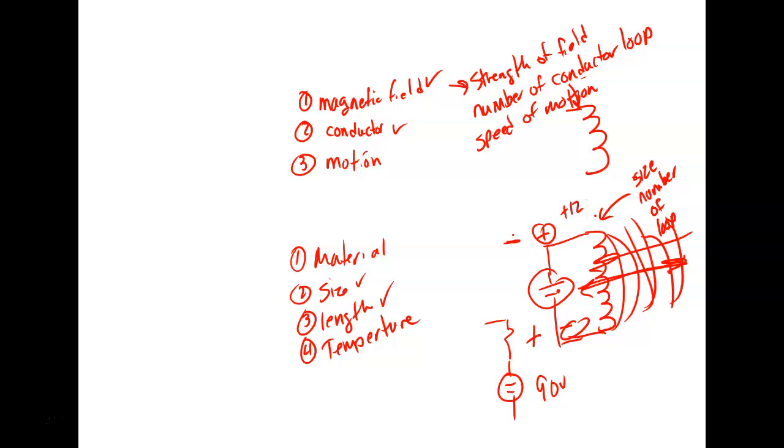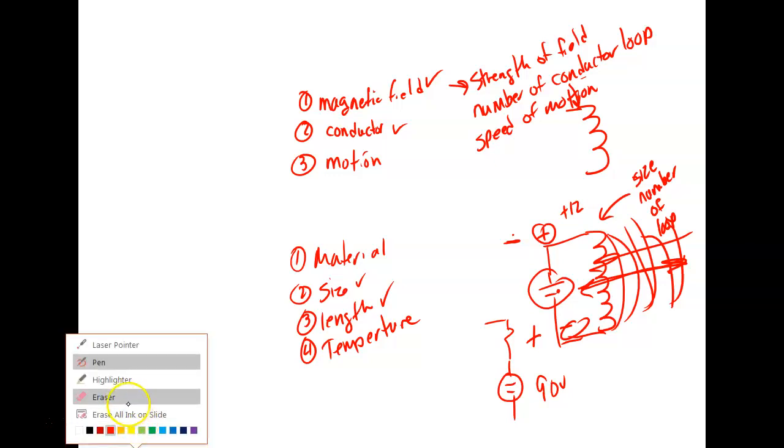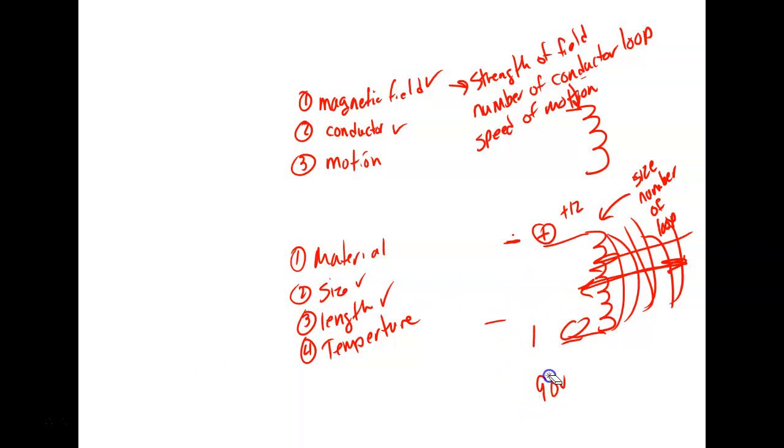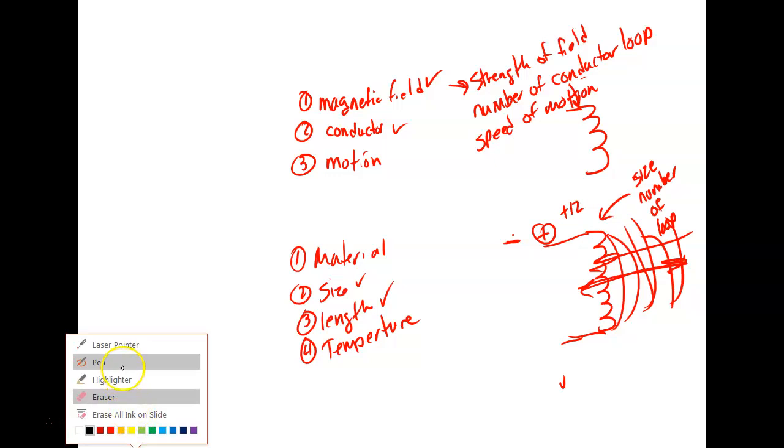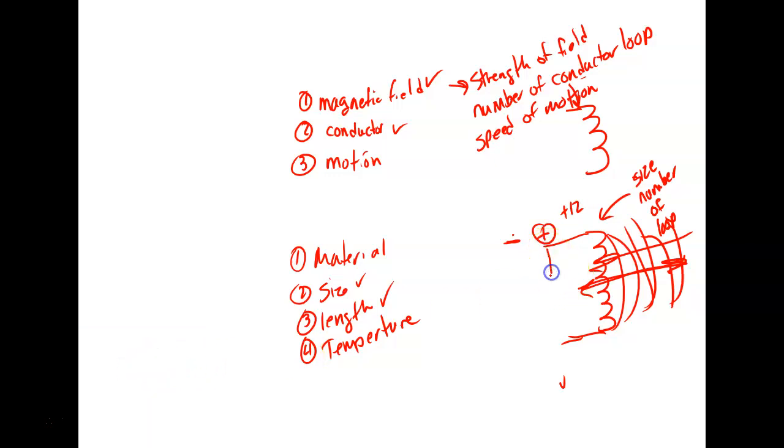Then when we turn that thing off, that light bulb comes on, which means the counter EMF that was generated was over 90 volts, even though I charged it up with what? 12. So anytime we have these DC coils, we put a diode opposite of the polarity of the applied voltage. So that means we would put the diode like that.